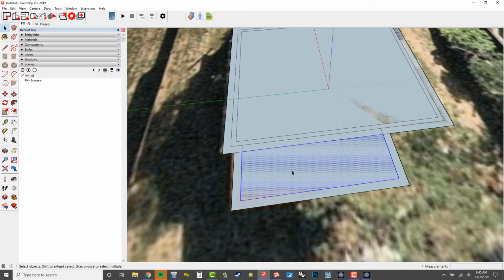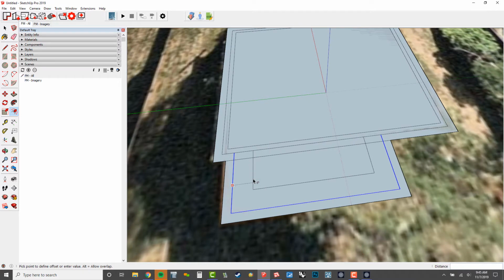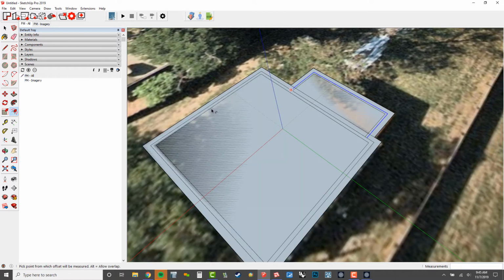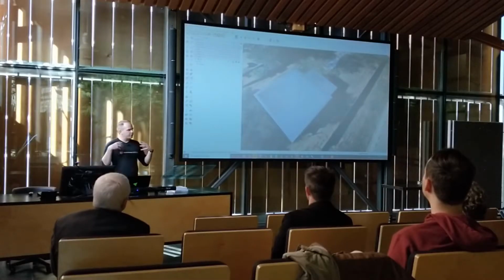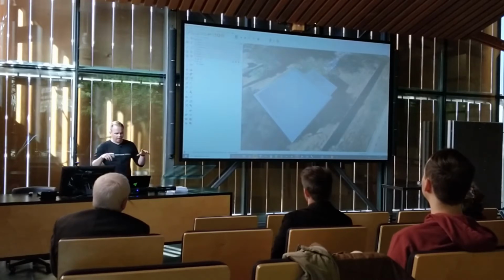And then I could take these lines and offset by say, that is a stick frame, so it's a different construction type. So we'll just say like 4.5 inches. Enter. So now I just have kind of a simple outline of this. One thing I didn't put in there is there's a front porch, but that's okay. You can just kind of get the general massing of the building. And then when you get to the site, it's super easy just to fill in the details rather than having to paste the whole thing off.